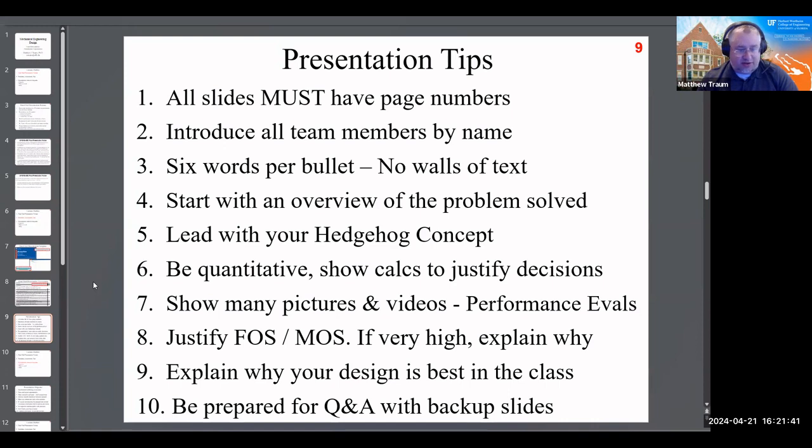In the automotive industry, you might consider a factor of safety of something like 2 or 3. They still have weight and cost concerns, but they're not nearly as severe as in the aerospace industry. And of course, in the auto industry, they could take on less risk than they can in the aerospace industry. So factors of safety are going to be higher.